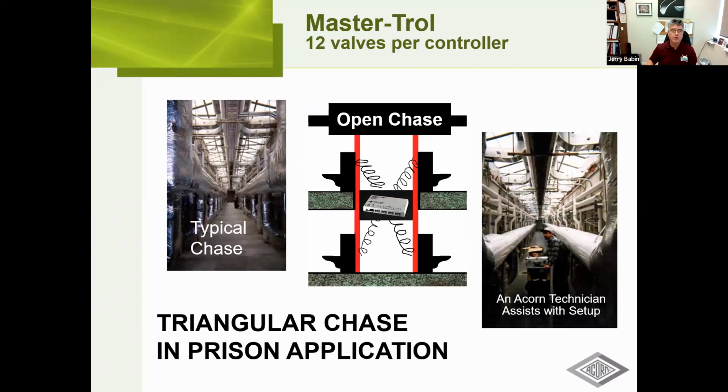Again, typical pipe chases, where does the controller go? Again, it would be in a pipe chase or accessible ceiling space if that's where it needs to be. Again, you've got a 10-foot distance, typically, is what we provide. You can go further from the controller to the fixtures, but we recommend 10 is the easiest because everything is nice and close proximity, controller to the fixture that it's serving.